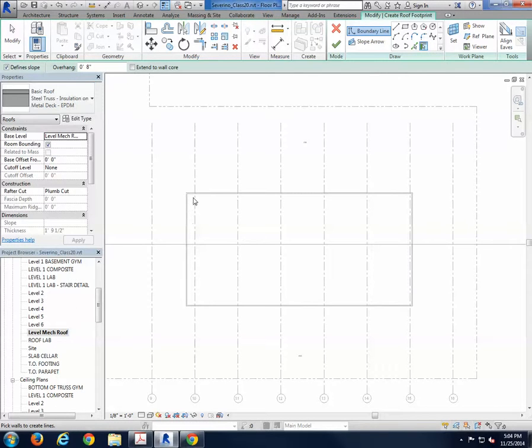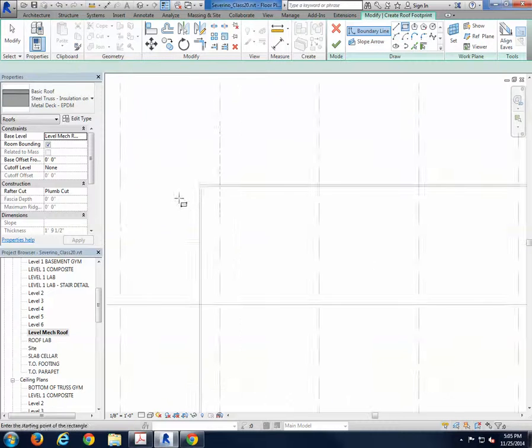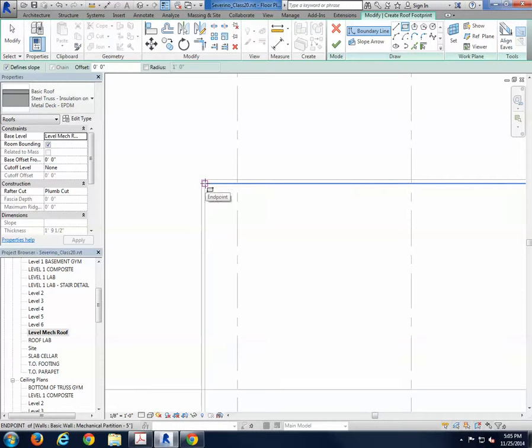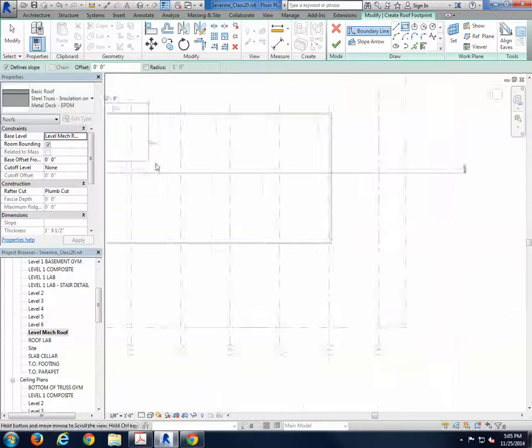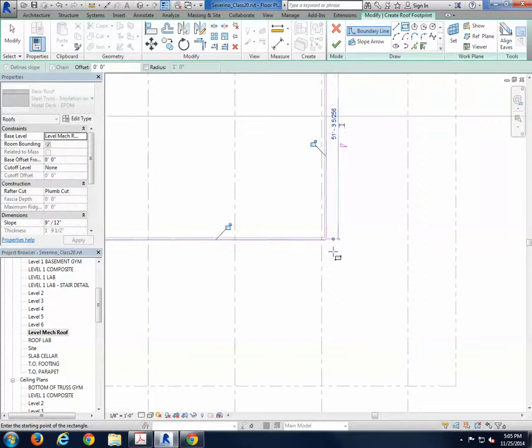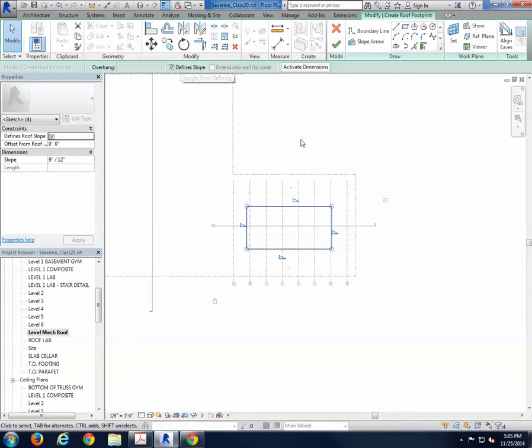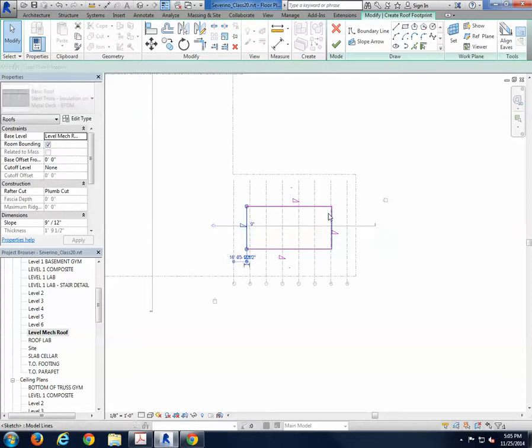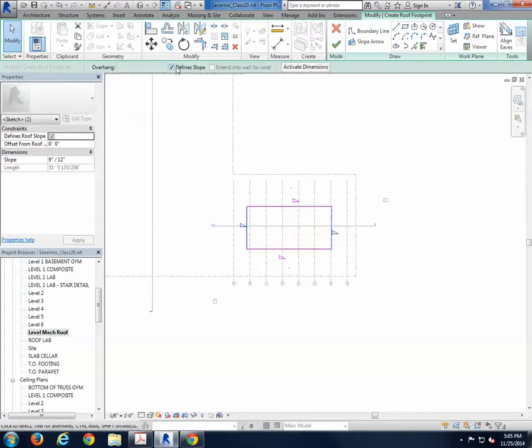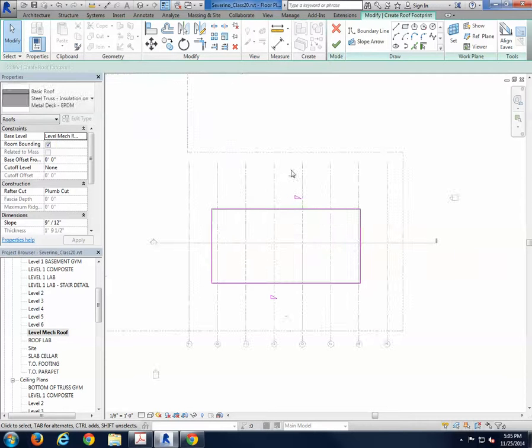Rectangle. I'm going to go from the interior, actually sorry, escape that, from the exterior to the end, escape, select all the lines. It's going to be a flat roof. Actually, why not? Let's actually not make it flat. Let's just make it angle from those two lines, so those won't have slope, and you say OK.